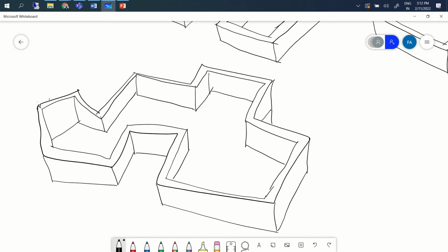Sir, but actually there's another doubt right now, if we go with the floor plan, then what about the orthographic view? What about the orthographic view means? Will it just be rectangles? If we project these sides, if we see from the right side or from the front elevation, it will be just rectangles with vertical lines dividing them, right? No, you add the windows, the openings, and then draw that. Okay, sir.